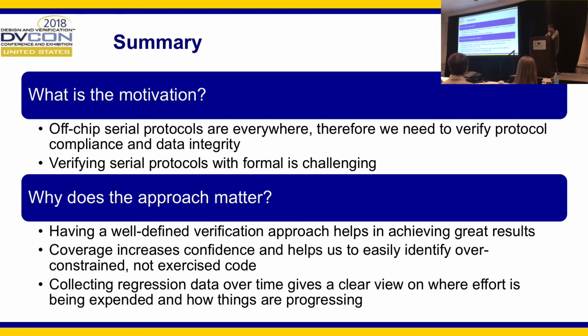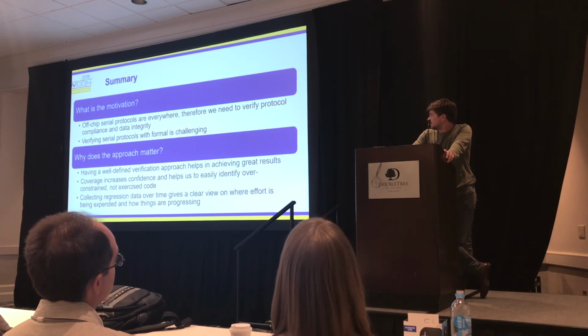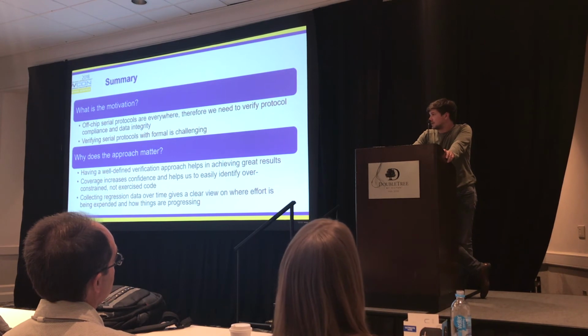And why does the approach count a lot? Because you have to have a well-defined verification approach when you start verifying design using formal. Why is it good to have coverage? Well, coverage increases confidence and helps to easily identify over-constrained code and unexercised code. And collecting regression data over time gives a clear view on where the effort is spent and how things are progressing.